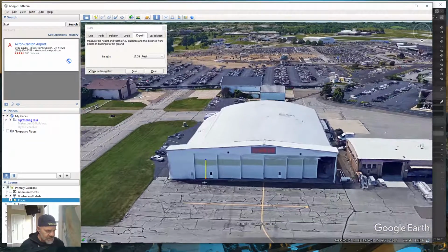That lack of shadow tells me that that door actually opens to the outside. So these people doors on the actual hangar doors would be flush with the outside face. This door over here has a shadow, so that's telling me it opens to the inside. It's inset into the wall. So that's how we're going to model this particular person door.